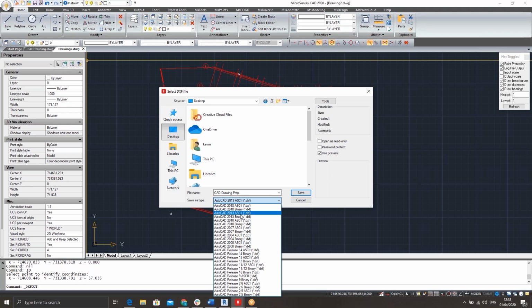The different versions can handle information differently and slightly better in terms of interchanging from desktop software into field software. So if you run into a case where you're having difficulties on import or something's not transferring correctly, it's not a bad option to look at saving it into a different version and then bringing it again into your field controller, and it might resolve your issue.